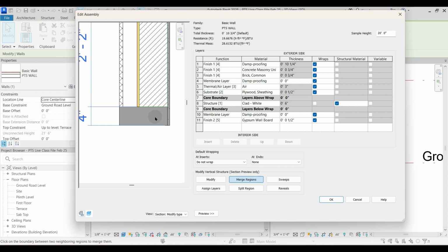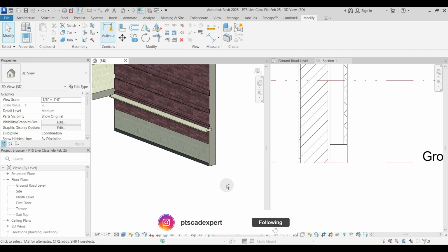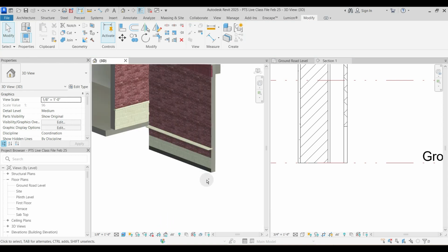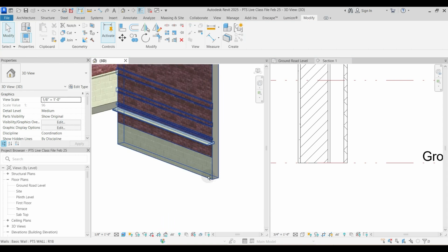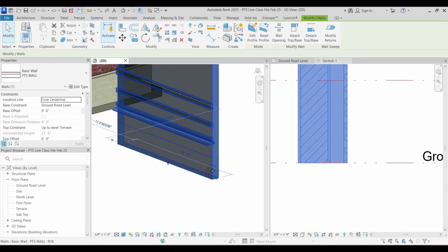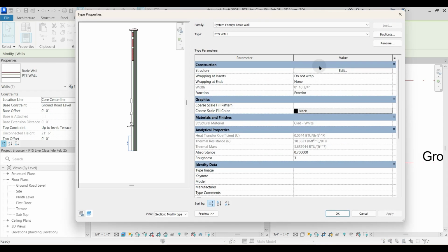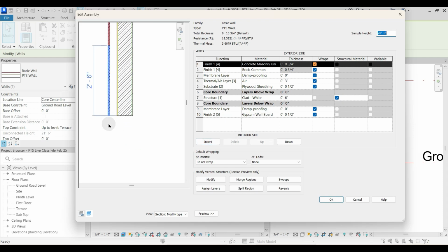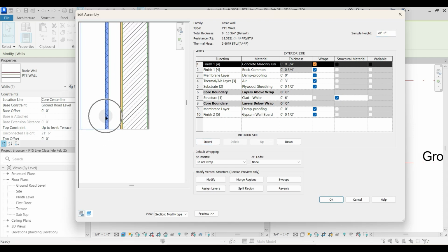So what we will do in this case is that I will just click undo until we are here. Okay. And instead of splitting the exteriormost layer, we will follow a different method wherein I will not split the non-membrane layer, but I will split the core layer and then flush it all the way till outside. So how will I do that?